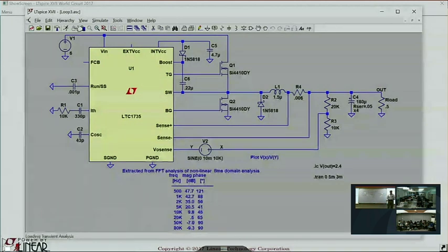People try to transcribe that to frequency domain analysis so you can do Bode plots and check stability, but it's really just nonsense. You should just look at it in the time domain. It's much more straightforward. But anyway, you want to add as little slope as possible so that you can avoid the high frequency instability, but not so much that you mess up the low frequency stability. So what you want to do is have a function.